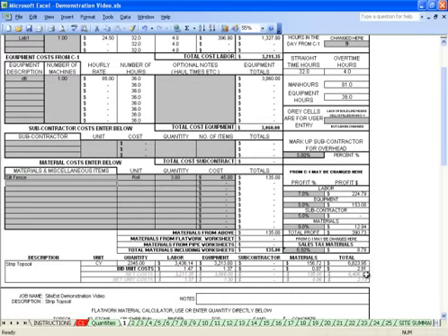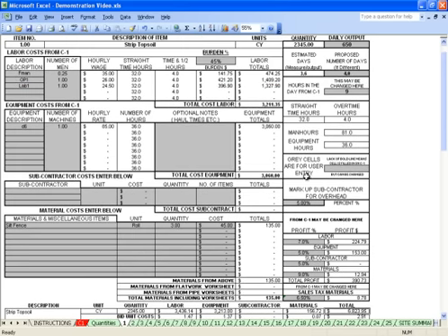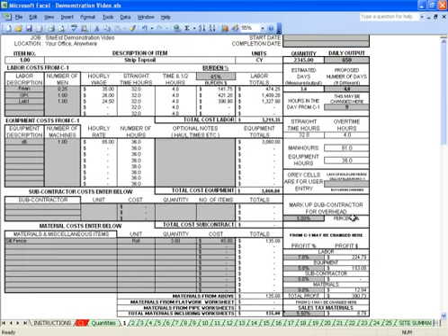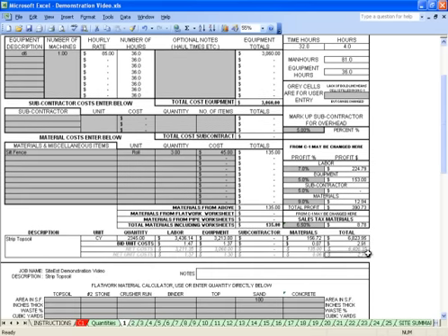That tells me I can strip that topsoil for $2.91 a yard, or $68.23, of which 34 is labor and 32 is equipment. I've got 32 straight time hours, 4 overtime hours, making 81 man hours, 36 equipment hours. I've got a projected profit of $390 with a net cost of $2.73 a cubic yard.